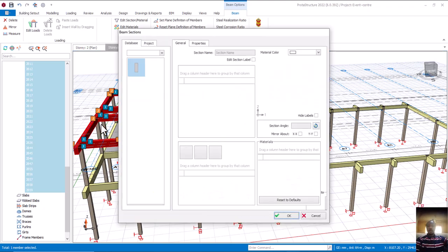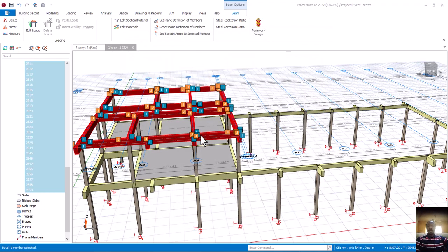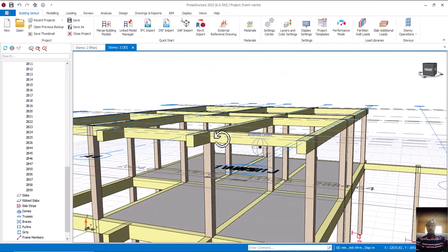We are using 450, and we have explained how we came about 450. On that ground, since there's no slab, I'm going to remove the thickness of the slab from this beam, which is 150. So here I'm going to have 300, which becomes my roof beam. I'll now click on OK. Correct. So everything has automatically been adjusted. Is that okay?